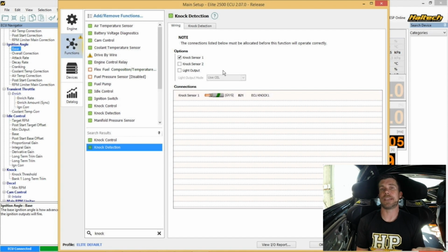So somewhere near the deck surface generally gives you the best signal to noise ratio from your sensor. Beyond that, I've also found that fitting the sensor low down on the engine block, or even sometimes on a cast sump, will still work well.